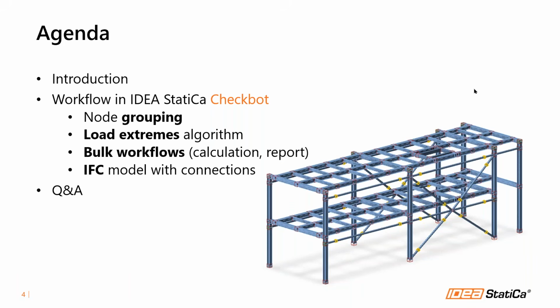We start with a brief introduction, then proceed with the description of the workflow in IDEA StatiCa Checkbot. We will work mostly in this program, but we also will touch a bit on IDEA StatiCa Connection, and we'll be talking about topics like node grouping, load extremes algorithm, bulk workflows, and IFC model with connections, so exporting your designs to an IFC file.